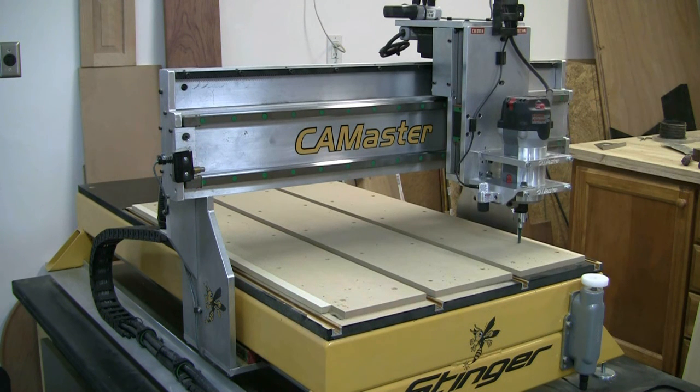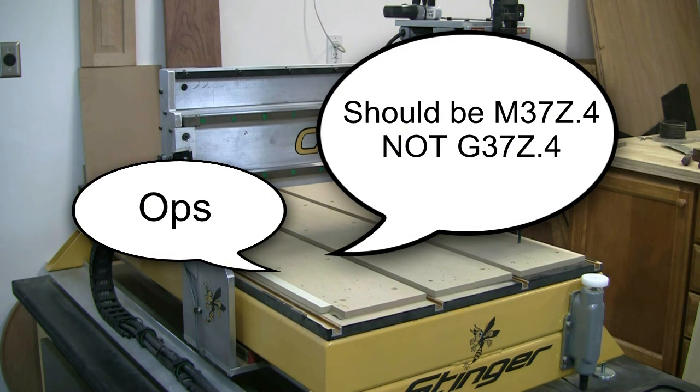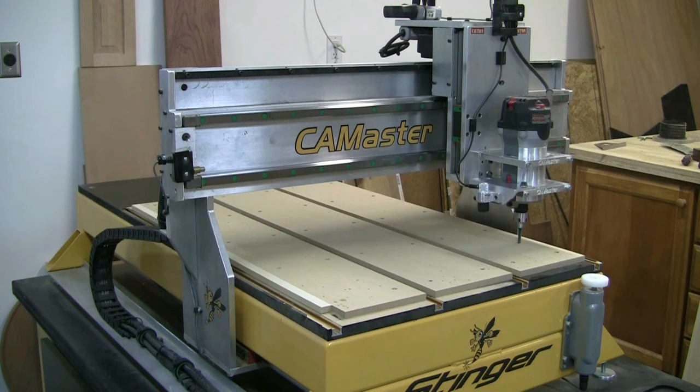So just a very quick recap. You lower the tool to the table or use your existing blue box. Type in M37 Z.4 in my case. Move it off the table, type in Z0, do a calibrate switch, run your toolpath. When you're finished, raise it 0.4 of an inch to bring it back to the original Z, then do a calibrate switch, and now we're back to where we were before we started.